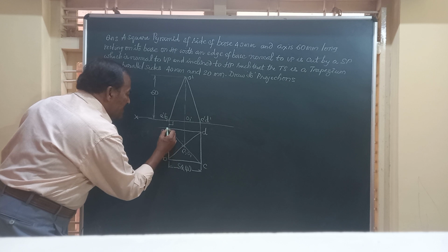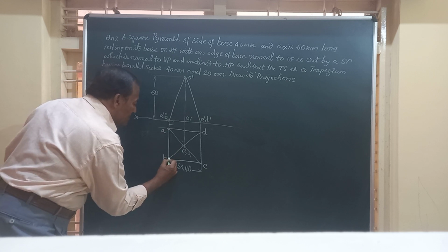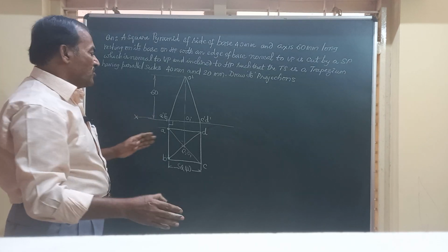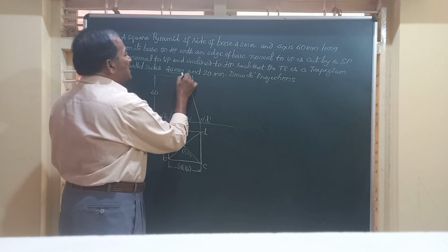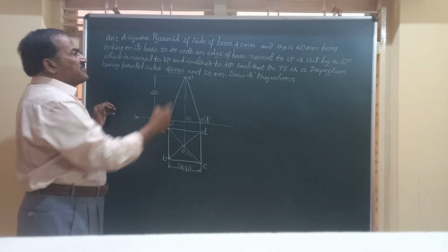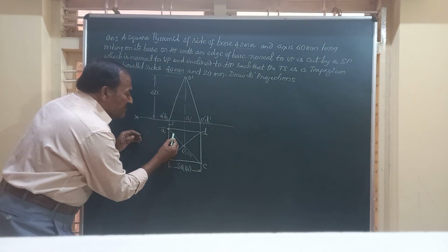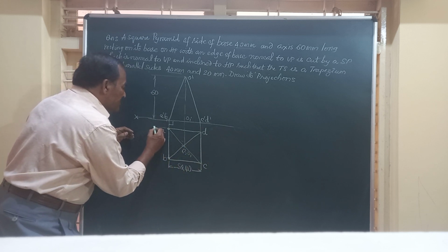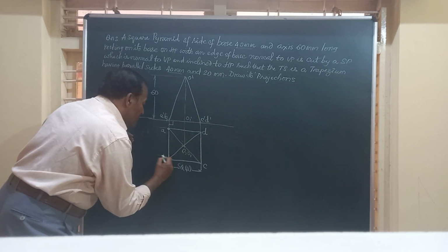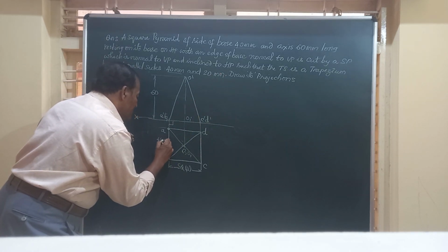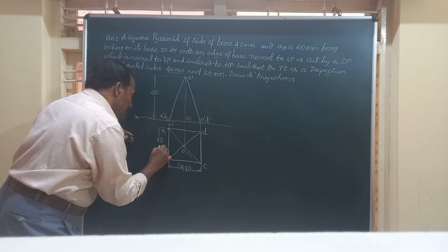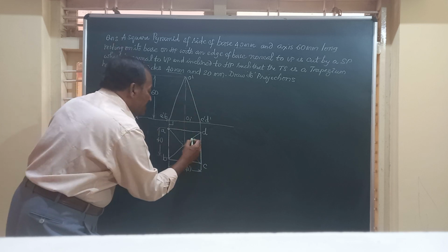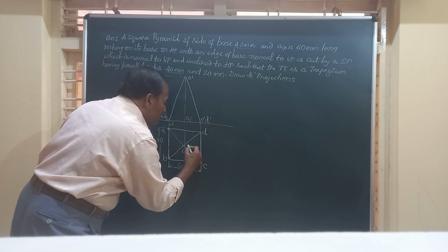I can take A as a point, B as a point. AB is one of the parallel sides of the trapezium because it has to have the dimension 40. If it were 30, we would have taken some distance, 30, from here. And the parallel side should have the dimension 20. So first I will mark here 40. 40 millimeter is this side AB of the trapezium in the true shape. And on CD, it should be 20. How to mark the 20 mm here?